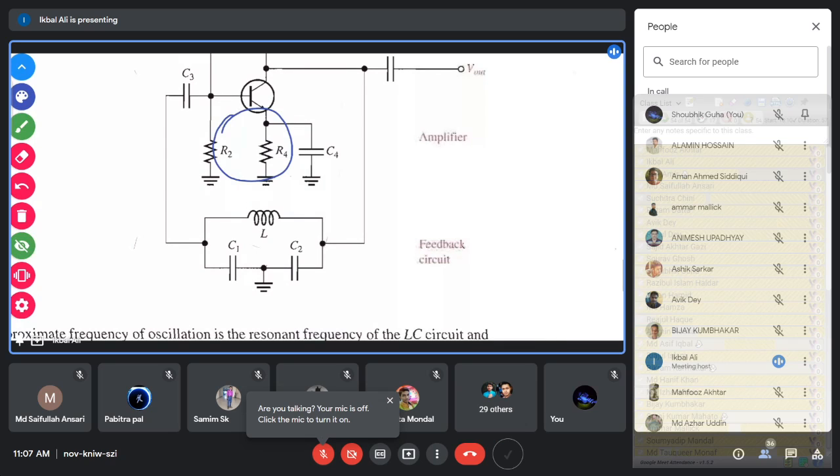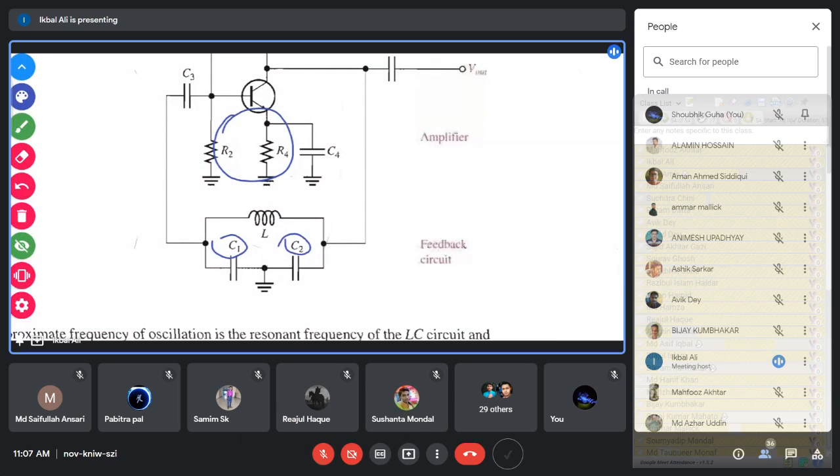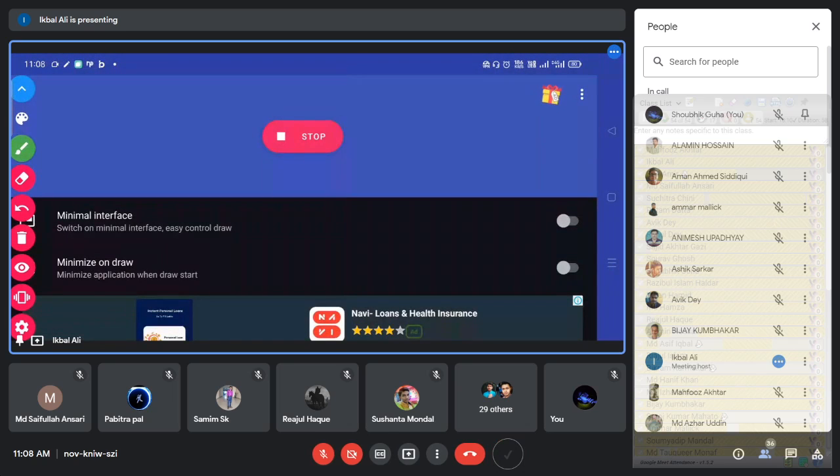these two capacitances C1 and C2 both have one end connected to the ground. If the two capacitors C1 and C2 were not connected to ground, then this stray capacitance would not have affected these two capacitors, but they are connected to ground. This is the reason: as it is connected to ground, the capacitance actually comes in through the ground.